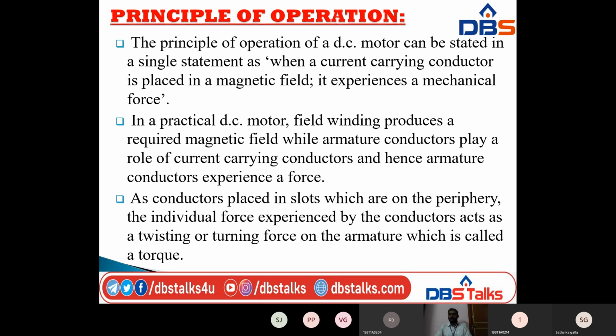Actually, in a practical DC motor, the field winding produces the required magnetic field, while the armature conductors play the role of current carrying conductors only, and hence the armature conductors experience a force.